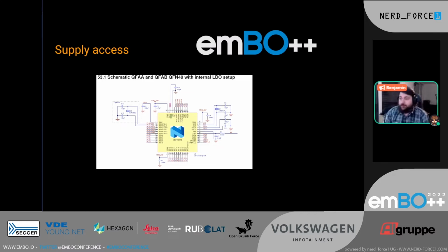So we can, of course, drop things like this with a crystal. We can drop this because there's also a crystal. Well, this connects two different lines via two capacitors. Well, that doesn't look good either. This does something weird, so let's also drop it. This connects to the voltage line, not interesting. And in the end, we are left with decoupling 1, connecting via a capacitor to ground, and decoupling 4, connecting also via a capacitor to ground.